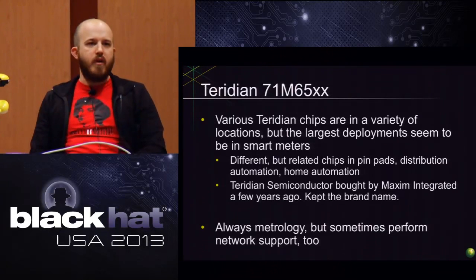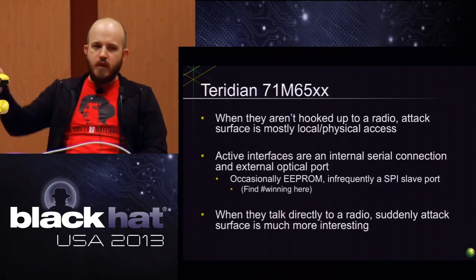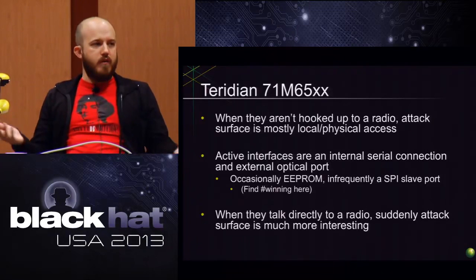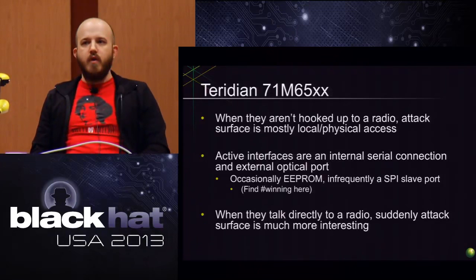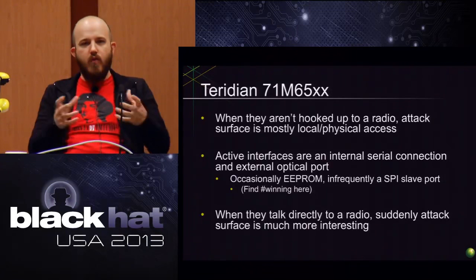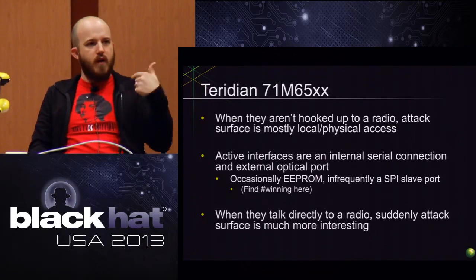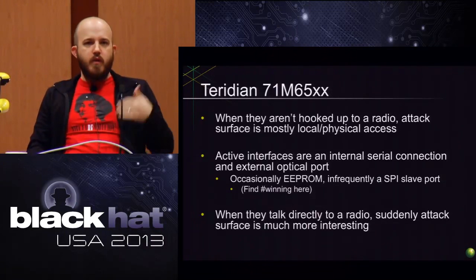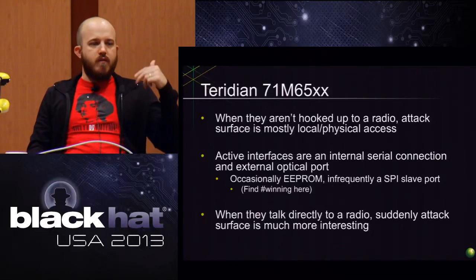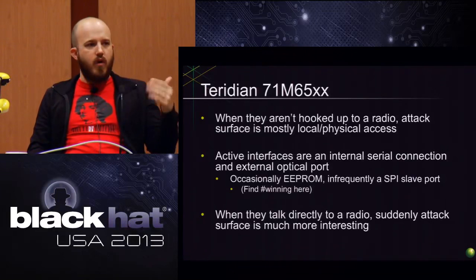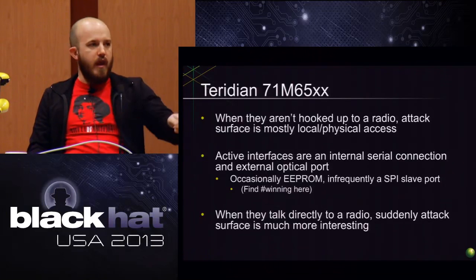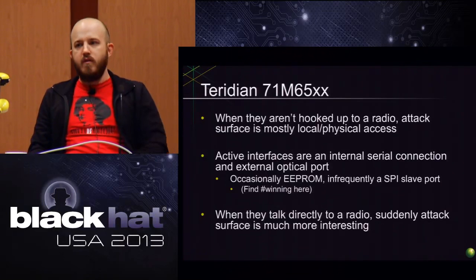That gets different. There's standard interfaces into this chip. Serial is the most common one, and then that can talk to whatever they want it to talk to. It could either talk to another board that is an entire computer in its own right, doing whatever it's doing, and it's just ferrying commands back and forth. Or it could just be doing straight pass through, and the Teridian chip itself could be speaking something like ANSI C12.22, which is the one for network communications, and then you've got actual packets terminating inside the Teridian chip itself.